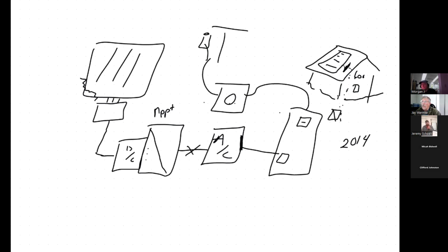It's just not practical. So then a company called Enphase said, instead of making one big inverter, let's make little tiny inverters that hook up individually to individual panels. So I'm going to put my little microinverter and attach it there. One panel, one microinverter. And at that point, as soon as it loses sight of the grid, it shuts off right at the panel. Problem solved. The only problem was these things were kind of pricey, like $200 a piece or so.